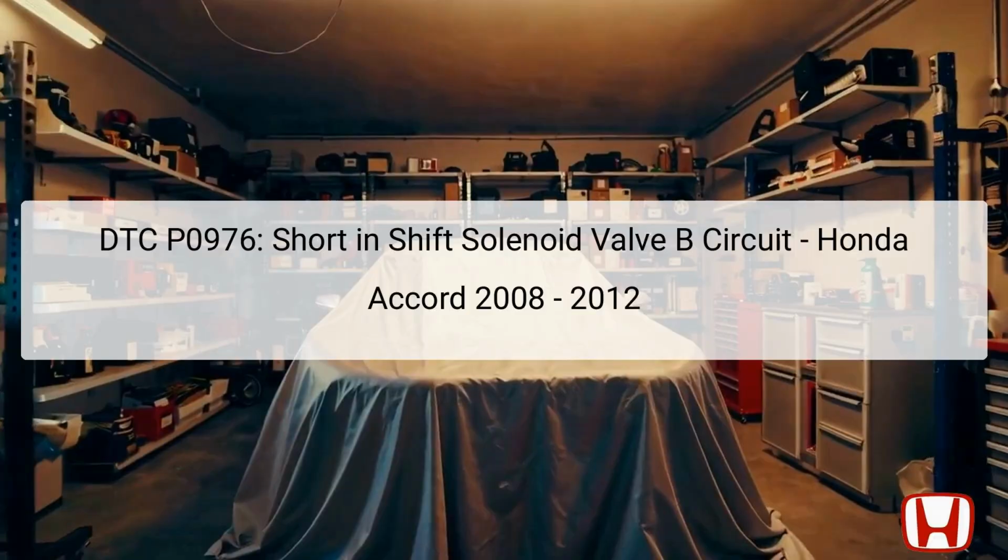DTC P0976 refers to an electrical issue within the shift solenoid valve B circuit in the 2008 to 2012 Honda Accord. This diagnostic trouble code, DTC, is triggered by an electrical circuitry malfunction rather than any mechanical faults in the transmission.